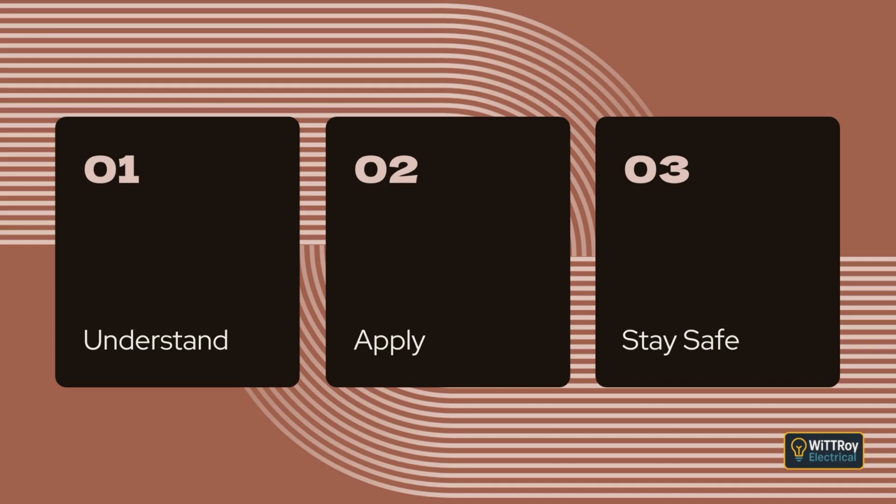The key idea: you can move the overload protection, but only if the cable is not placed at risk in the unprotected section. Clause 2.5.3.4, Omission of overload protective device. In some situations, overload protection may be intentionally left out.